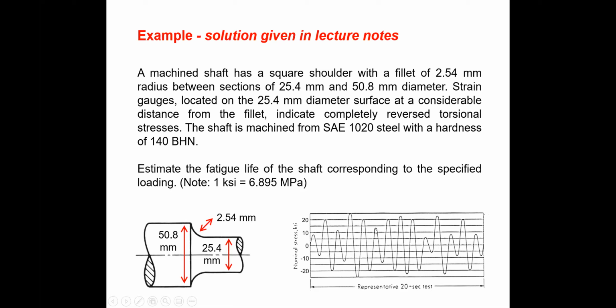This is around 13, something like that. So you can count like that and get the frequency of each stress range, and then you can convert the stress range to megapascal. You can't use that equation for the KSI, so convert to megapascal.